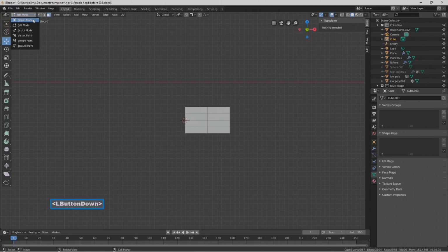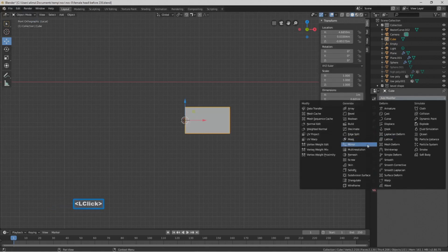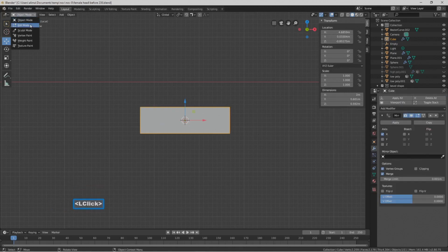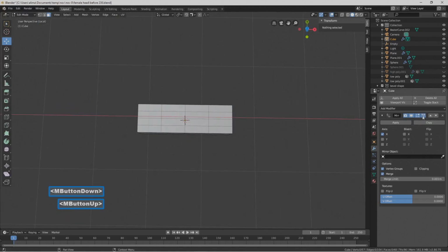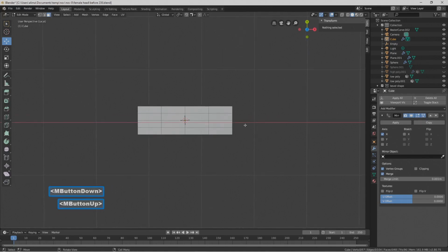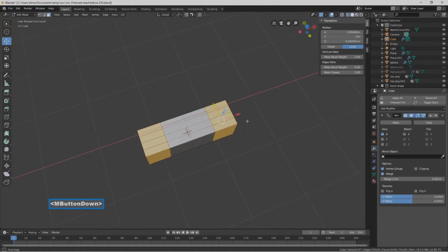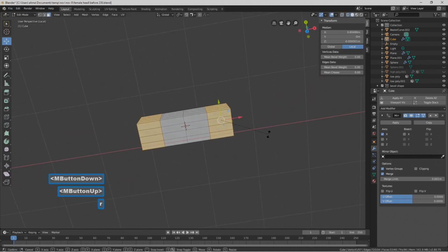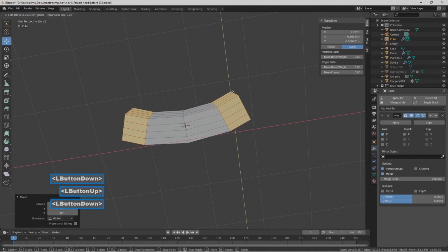I'm going to go back to object mode, go to the modifier, select mirror modifier, go back to edit mode, hold the middle mouse button to rotate the view. Select this triangle with circles on it. I'm going to press Z, go to wireframe, hold B, select right there, press Z, go to solid view. So we're in a top view. I'm going to press R to rotate, pull down this way, pull out some like this.